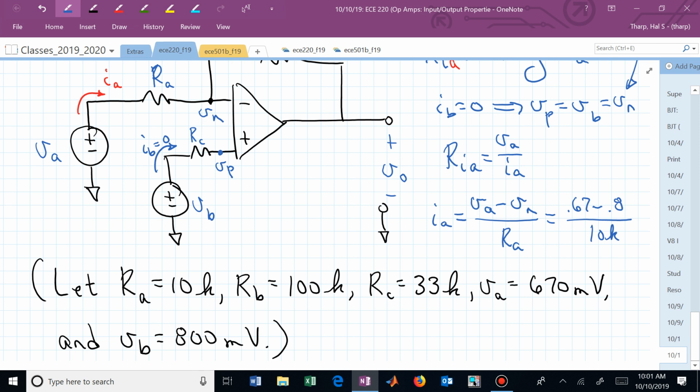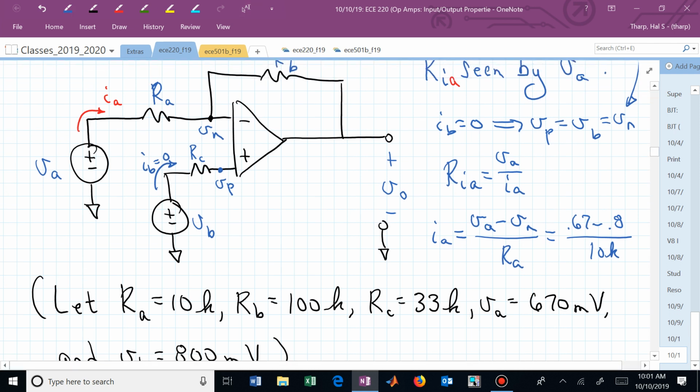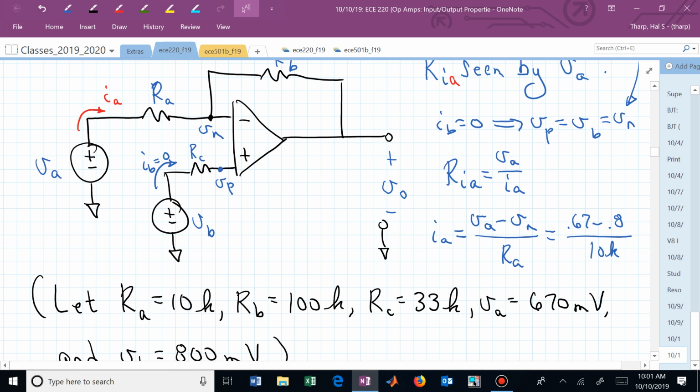But now what we've learned is that, in fact, this current that I've labeled in the direction I sub A is not going in that way if we interpret the sign here. It's actually, the current is in fact going into the A voltage, V sub A, which means we're charging this source in a sense. So all bets are off with this calculation.